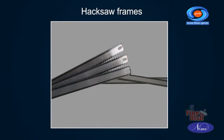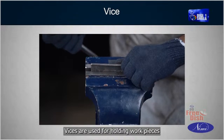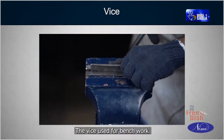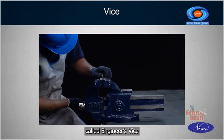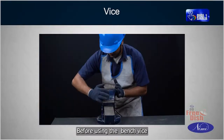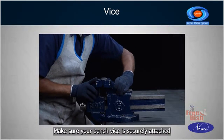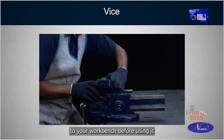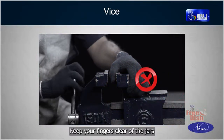all times. Vices are used for holding workpieces. They are available in different types. The vice used for bench work is the bench vice or called engineer's vice. Before using the bench vice, make sure your bench vice is securely attached to your workbench before using it. Keep your fingers clear of the jaws.